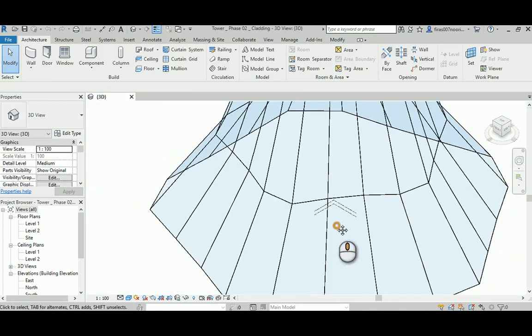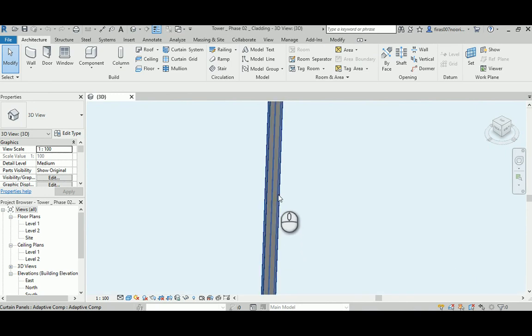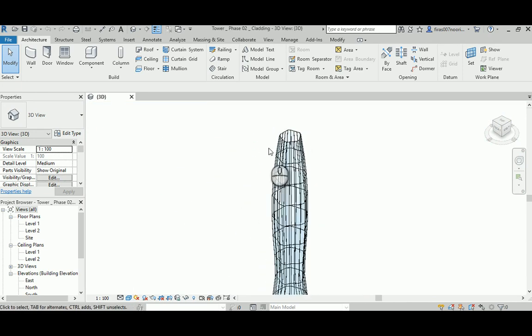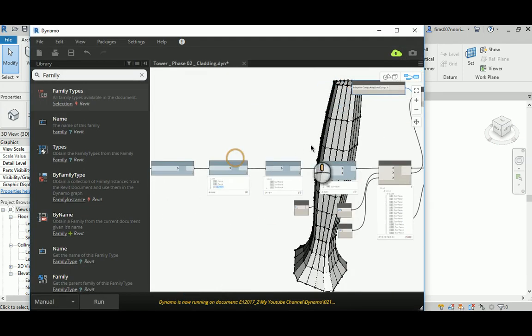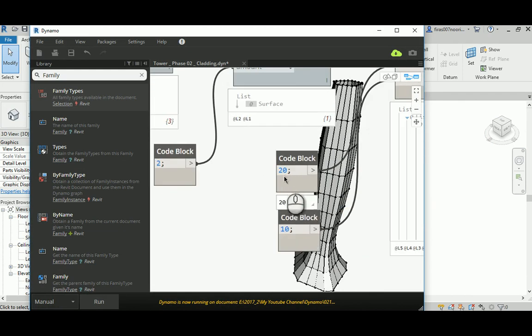Probably you need to go and increase the thickness or make that frame parametric, actually the width, or even much more crazy thing to be done is to go to Dynamo itself and increase the amount of here U and V's, probably you need 30 by 60 or 60 by 30, I don't know. Just go ahead and see how much your machine can take and how much time you need to do that.